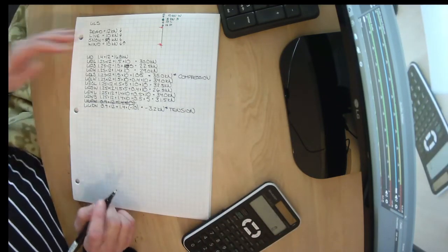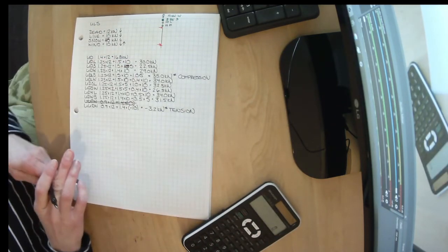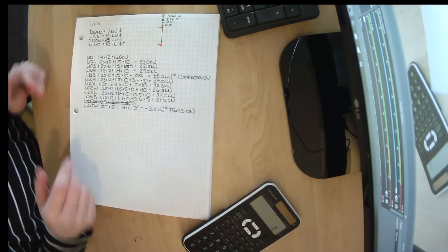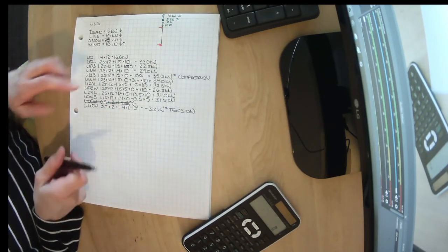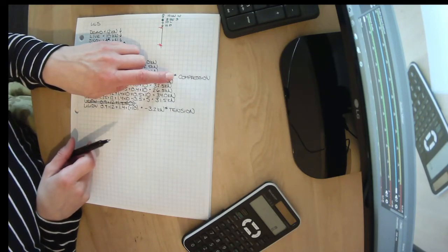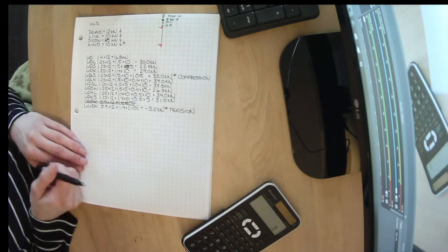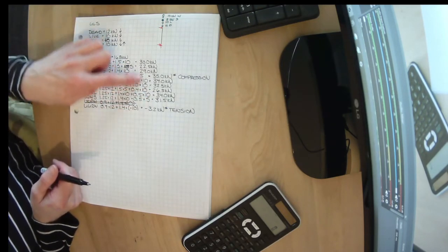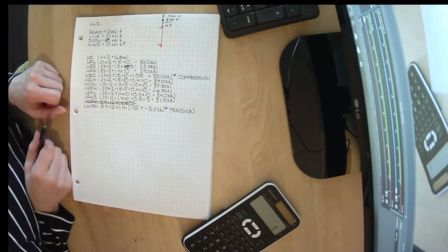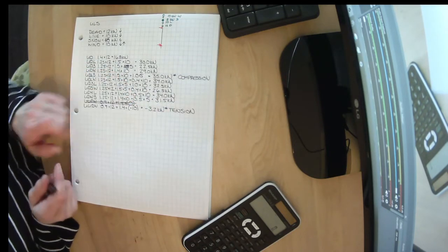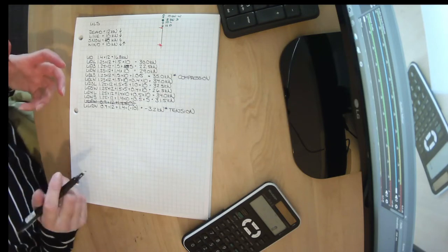So we have to design for all of these load cases. We need to make sure all of these are less than our reduced capacity. And next term, we're going to figure out how to calculate the reduced compression capacity and the reduced tension capacity. Well, if all of these are in compression, you might as well only worry about the worst case one. And if these are the tension values, you might as well only worry about the worst case one.